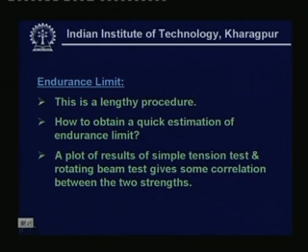So, a designer always wants to obtain a quick estimation of endurance limit without going through such a lengthy procedure. It is possible that a plot of results of the simple tension test, which is a relatively easier and quicker procedure, and the results obtained from the rotating beam test can give rise to some correlations between these two strengths.